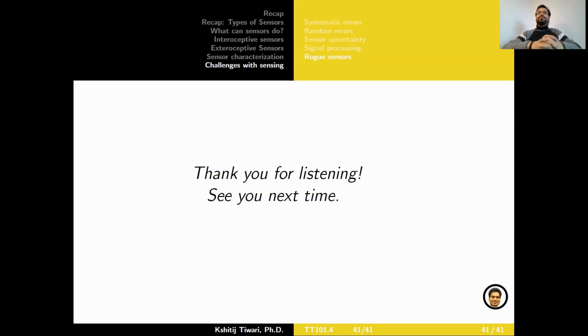And then we looked into various challenges of sensing, both in terms of a fully working sensor and the noise and the uncertainty that exists with it because of the things that it can and cannot measure, and also in terms of rogue sensors and the amount of extra effort you need to put in to clean up the data and make some sense of the data if you're using sensors for mobile robot navigation. All right, with that, I wrap up this lecture.